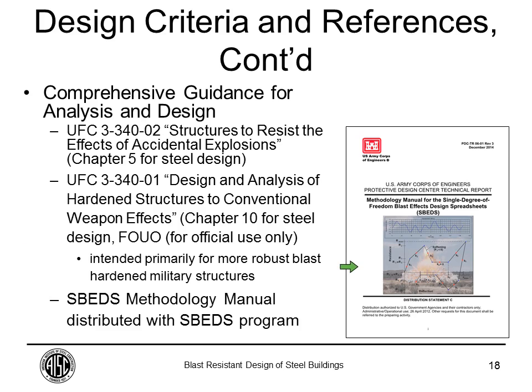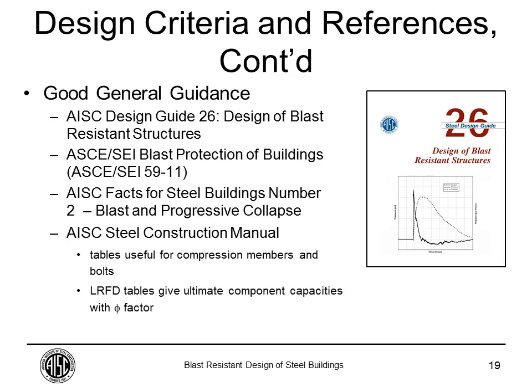So if you're in that range where you're familiar with blast loads, you're just looking to take it to the next step, instead of understanding a little bit more how do we apply the tributary width and how do we check connections and things like that, I recommend you read the methodology manual for SBES because it's very good guidance. And finally, we have more industry criteria that has been developed that provides really good guidance on the application of blast loads and the design of blast-resistant building and components.